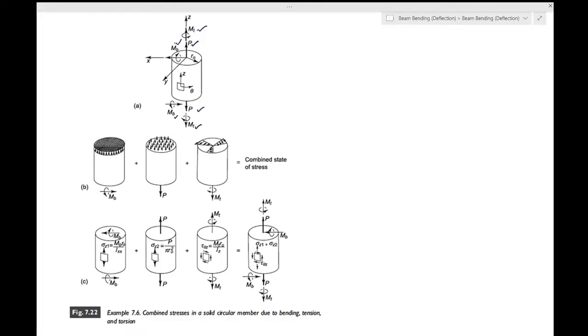Yes, it was example 6.3. So please go back to the torsion chapter and you can have a look at example 6.3. Okay, so we have the bending, which is in addition. So our method of approach is exactly parallel. In figure 7.22b, the individual stress distributions are sketched for the separate loads. Let's start with the easiest one. I always find the axial loading easy.